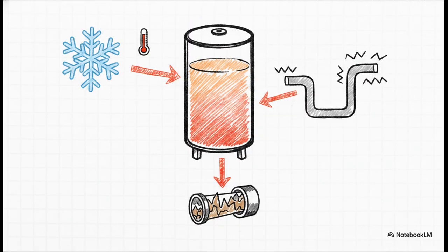And honestly, recovery speed isn't the only real-world factor you're fighting against. I want to highlight the stakes here by pointing out these specific conditions that will silently eat away at your system's output capacity if you ignore them. We already mentioned seasonal inlet variability, but what about storage temperature and mixing losses? Or the heat you lose as water travels through long recirculation loops and distribution pipes to get to those remote fixtures? Oh, and water quality and scaling, which actively reduces your heat transfer efficiency over time. You have to calculate for these losses, or your system is going to be effectively undersized from day one.